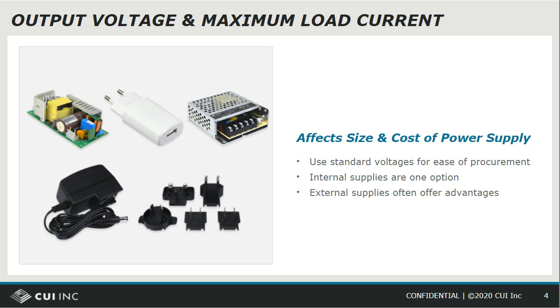And the reason for this is many factors lead into this, but shorter output cables from the power supply to the load means that there's less voltage drop along the cables with changes in load. And then on many internal supplies, there's the feature of remote voltage sensing. What this does is takes an extra pair of lines and runs it directly to the load. These are non-current carrying lines. They're just sensing lines. It enables the power supply to set the voltage at the load to the desired voltage. Again, an internal supply, for a number of reasons, will tend to provide a more accurate voltage delivery.